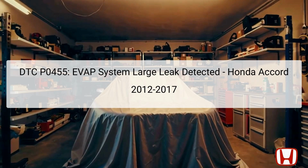A large leak can be caused by various issues, such as faulty fuel fill caps, damaged vapor lines, or defective valves. When the system detects it cannot maintain proper vacuum or pressure, an error code P0455 is stored in the vehicle's PCM, warning of potential emission leaks. Proper diagnosis involves following specific steps to pinpoint the faulty component without causing damage to the EVAP system. Correctly solving this DTC ensures optimal vehicle performance, compliance with emissions regulations, and prevention of potential fuel tank damage.